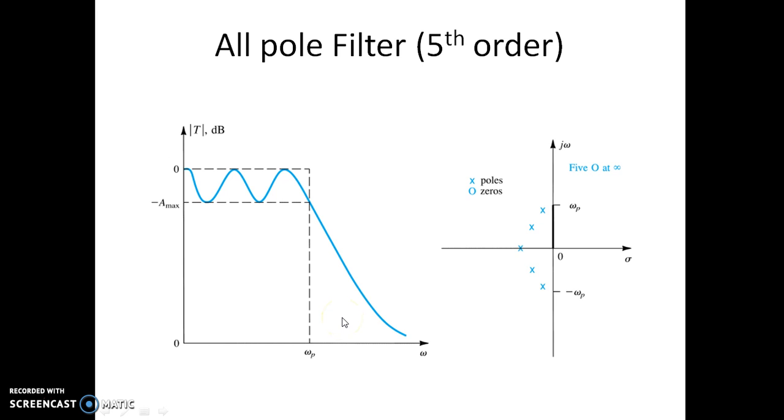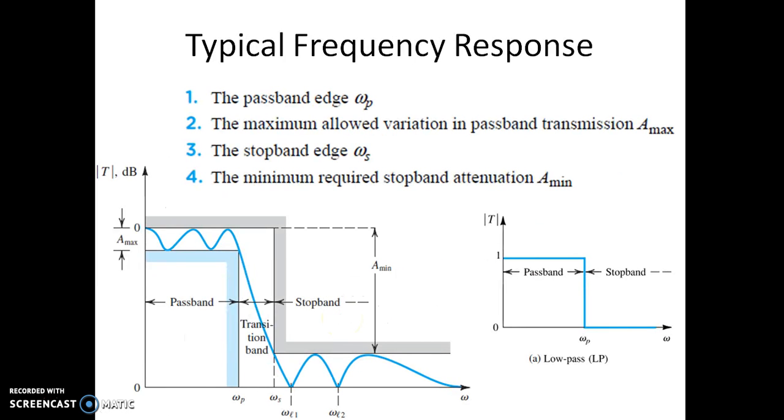As you can see in the previous transfer function, this is touching the x-axis, and this is also touching the x-axis. Whenever you have the plot touching the x-axis, this corresponds to 2 zeros. So there are a minimum of 4 finite zeros there, and this is a zero corresponding to infinity.